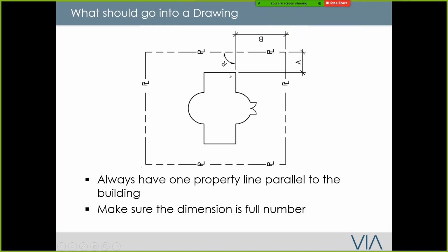That way, when you start a grid, this is the starting point of the building. I always do this in any construction drawings if you're building a new building. That way you just tell the contractor the starting point. They use an equipment, go to the property line, and then measure off from the property line. That's how they start. I always do this because it's about telling them exactly where the building sits in relation to your property line.